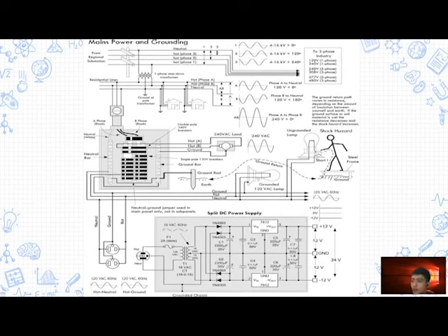The A phase and B phase wires that enter the main panel are connected to a main disconnect breaker, while the neutral wire is connected to a terminal referred to as the neutral bar or neutral bus. A ground bar may also be present within the main circuit panel. The ground bar is connected to the ground rod or the foundation steel support.